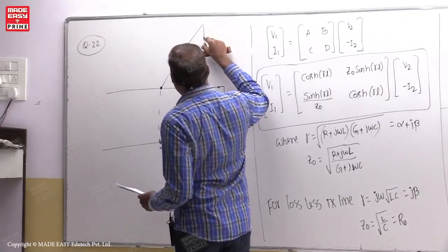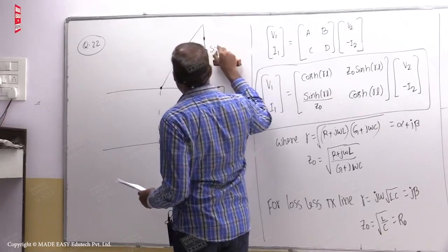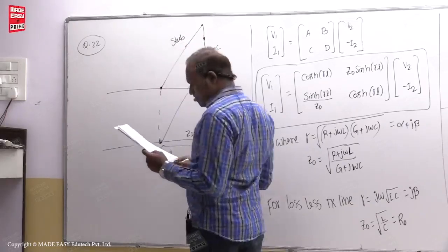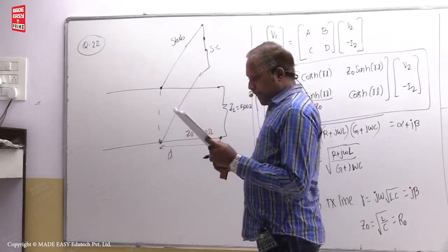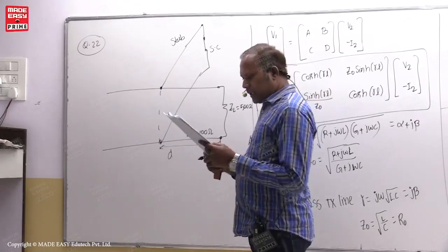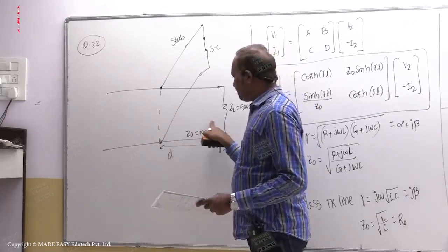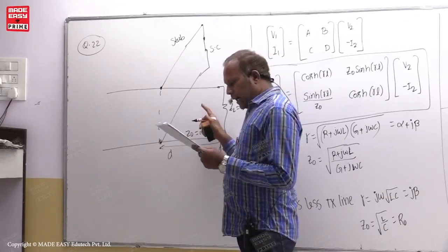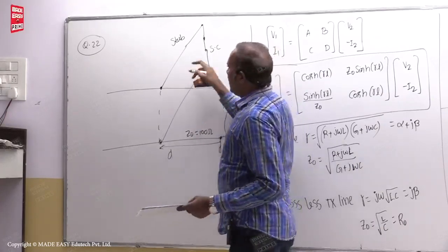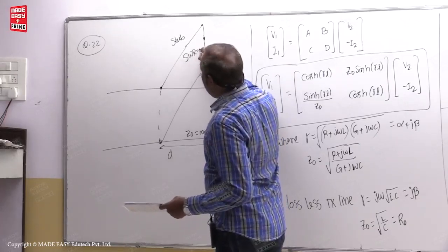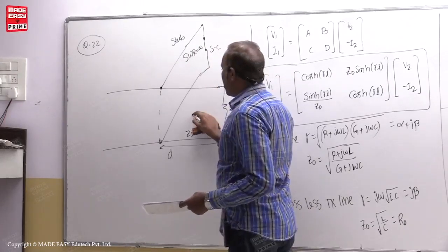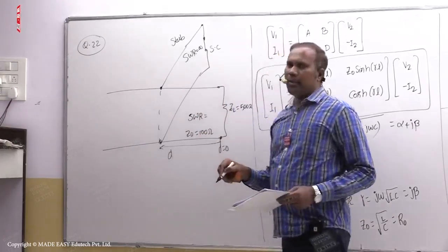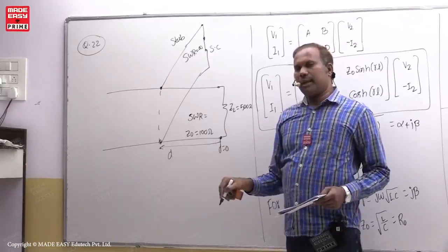That is actually a short circuit stub. So this is the stub. The VSWR on the length d, that means this length, students, and the stub itself will be, anyway, VSWR of stub is infinity. Next, VSWR is equal to, first gamma L is ZL minus Z0 divided by ZL plus Z0.